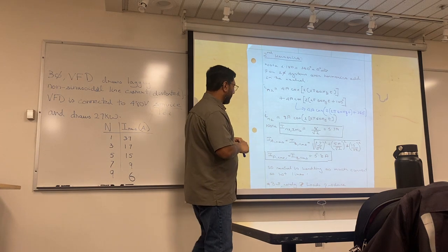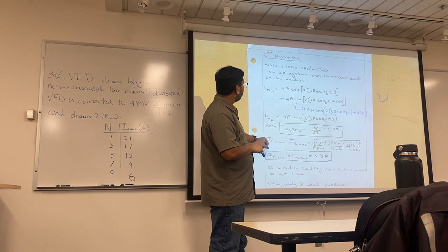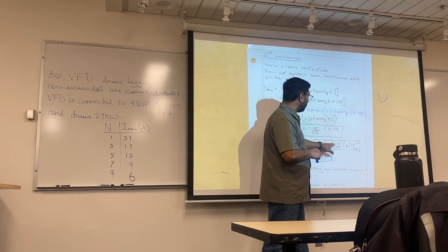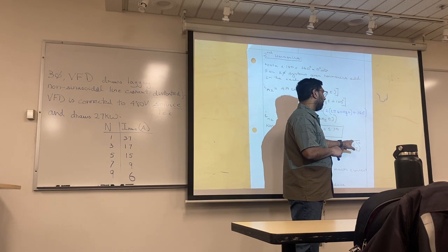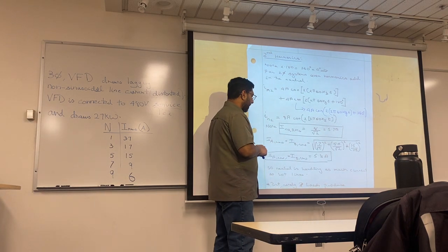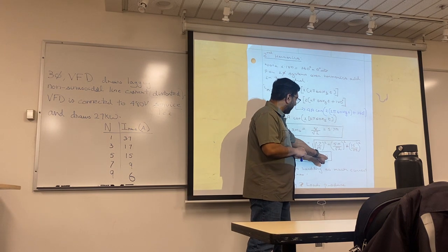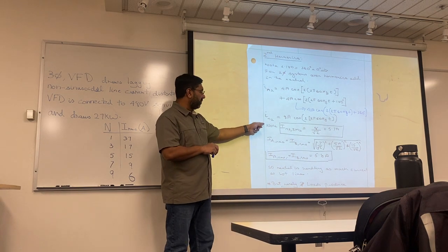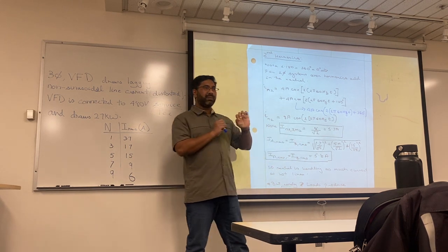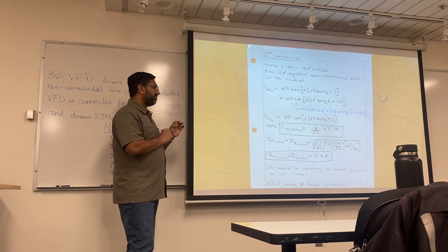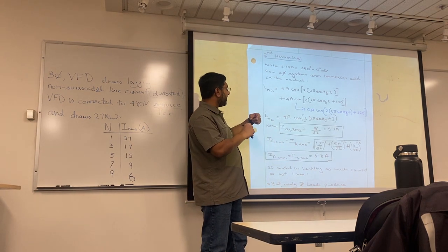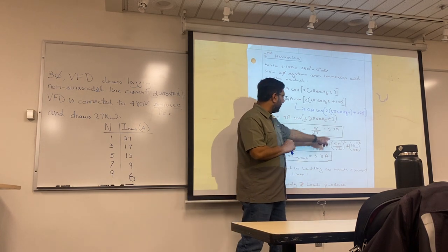Now I just went a step ahead and checked what the IA RMS was. That's coming from, remember the 3 currents that we had? 7 ampere at 60 hertz, 5 amperes at 120, and 1.5 amps at 180 hertz. I did an RMS square, just to find what my RMS currents were. And for a 2-phase system, it's 5.8 amps. This is the reason at home, when you're looking at your neutrals, you will end up sizing your phase and the neutral with the same cable or conductor. They may or may not know the physics or engineering behind it, but unknowingly all that you're doing is you figure out your phase, and because of the way the connection is made, the neutral is more or less the same. I mean, 0.1 ampere, you're not going to change the conductor.